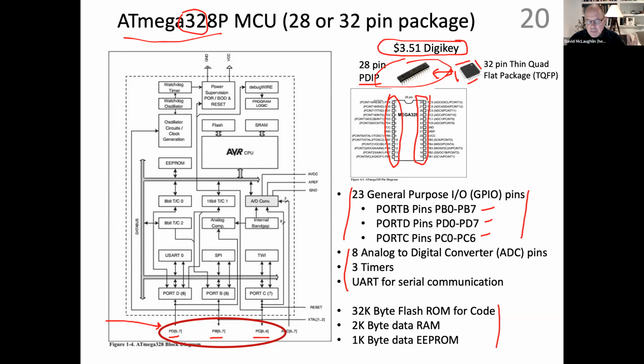You have to really be careful. If you don't know what you're doing and you start to mess around with the fuse bits on one of these chips, it's very easy to brick it. It's very easy to get it to a point where you can't access it anymore. So these questions of bootloaders, fuse bits, changing the clock, we'll get to those, but later on.